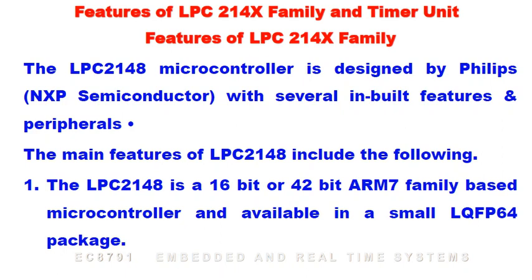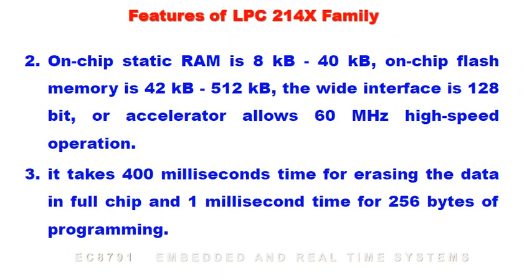The main features of LPC2148 include the following. The LPC2148 is a 16-bit or 32-bit ARM7 family based microcontroller. ARM means Advanced RISC Machine, and it is available in a small LQFP64 package IC.